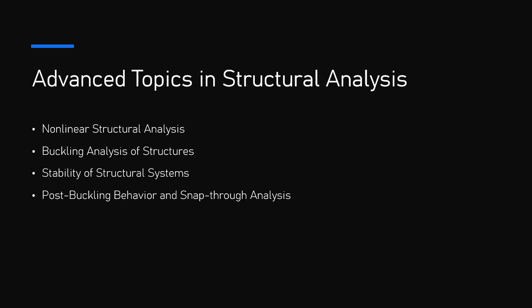10.3. Buckling analysis methods. Various methods are used to analyze buckling behavior in structures. 1. Analytical methods. For simple cases like columns or beams with uniform cross-sections and ideal boundary conditions, Euler's critical buckling load formula provides an exact solution. For more complex problems, such as structures with varying cross-sections, more advanced analytical methods, such as the energy method or Rayleigh's principle, can be applied.